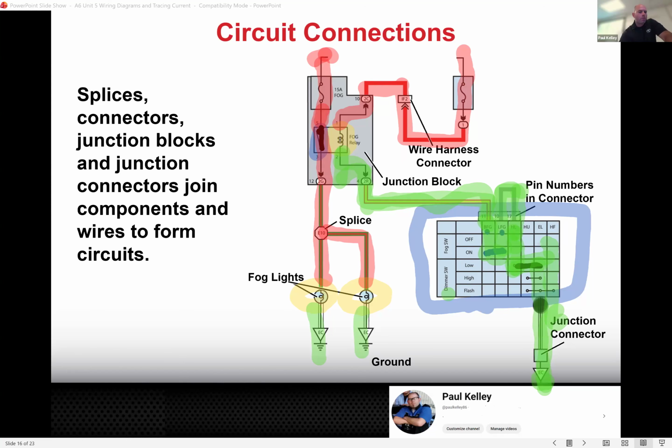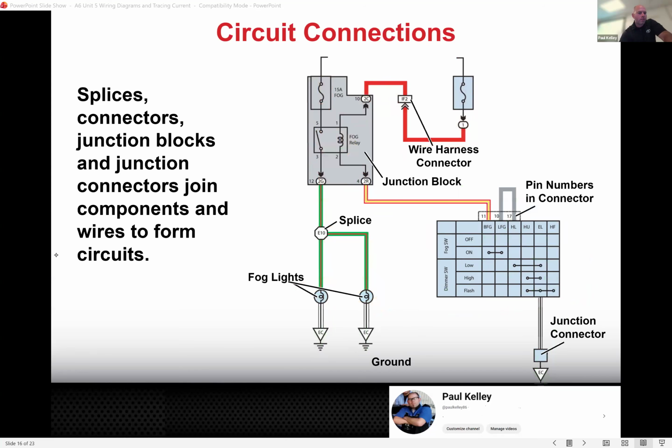here that's here to help you do your diagnosis. So if I were to erase this and just point a few things out, we'll do the green. This has the fuse labeled. This has a terminal, a terminal, a terminal, a terminal for the fog lights, and the fog lights labeled. This has a connector number 2G, terminal 12, 2R, terminal 4, splice E10, ground EC and EC.